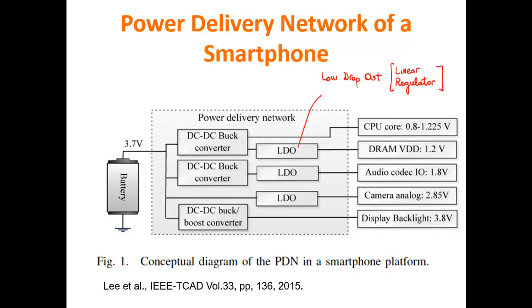Which has the property of being able to provide a more constant and better regulated voltage. This is required in order to supply power for the DRAM, because if you have a voltage that changes, this change can inadvertently switch some memory content. It can provide a disturbance that can switch some memory content, maybe with a low probability, but in a large DRAM, some errors like that always happen.